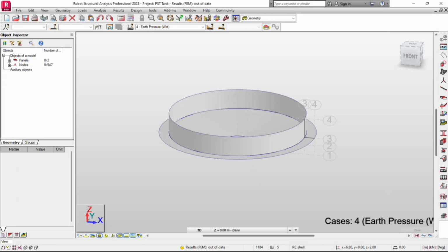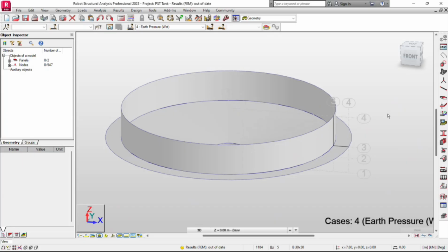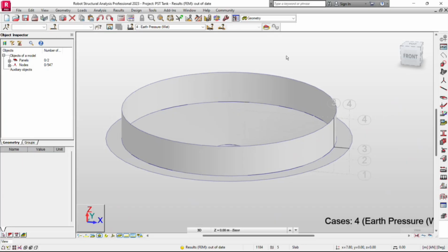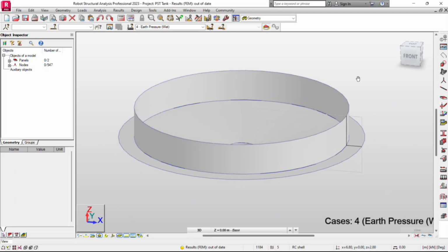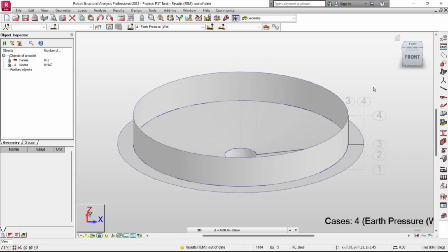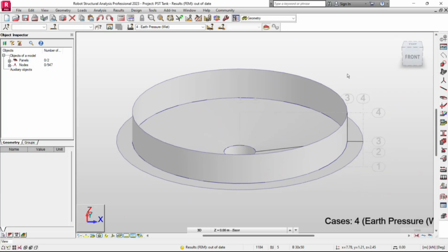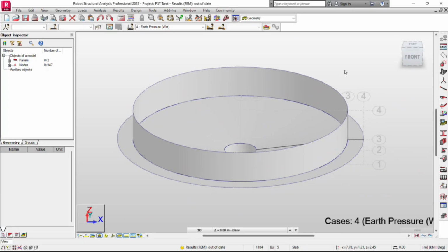Okay, it's done similarly to the earth pressure dry, but here it's quite a bit tricky because for the backfill of 1 meter, we assumed that the level of water rises up to the ground level. So the soil around this PST is going to be fully saturated. And when it's fully saturated, you know, the buoyancy force is actually acting already. It means that we're not going to be using the bulk or the saturated, but rather we're going to use the effective unit weight. What's effective unit weight? It's basically the difference between the gamma saturated less water, because you have to deduct the buoyancy force in there, right?